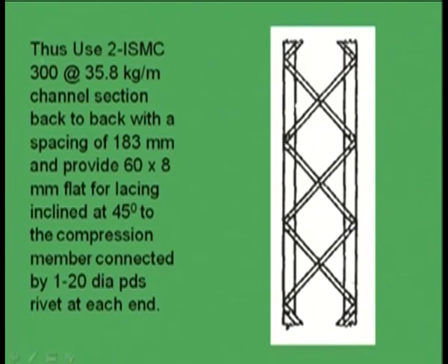It depends on the length of the built up section, spacing of the built up section and the compressive load, because 2.5% load is going to be carried by the lacing system, which was for shear, which has to be checked. So, all these things we have to see and decide. Basically, the design engineer can choose from their experience whether to go for a single lacing system or double lacing system.